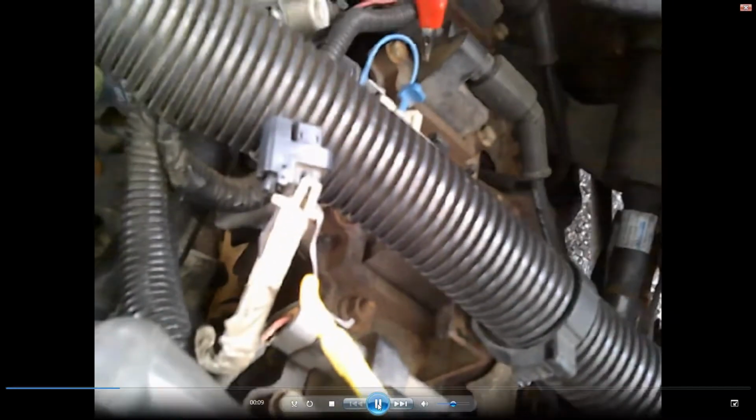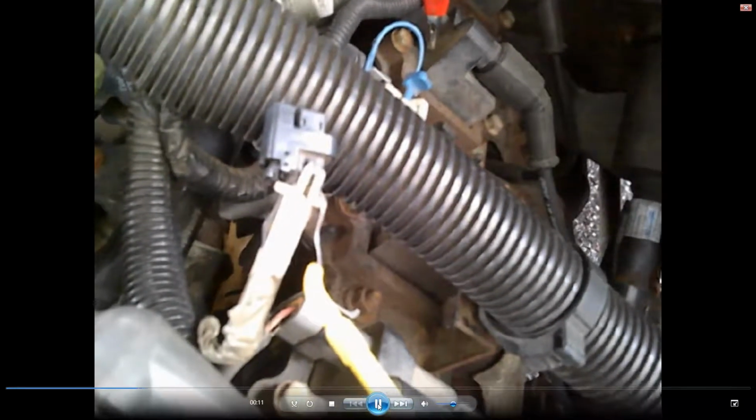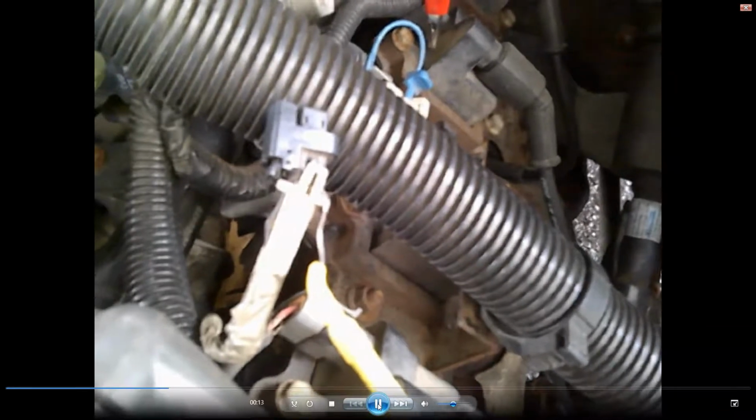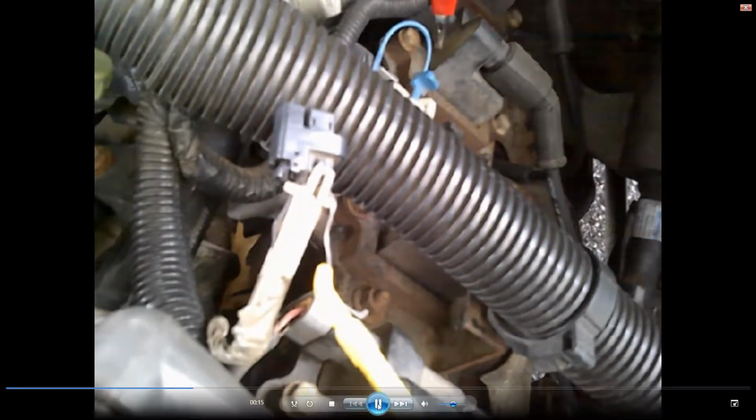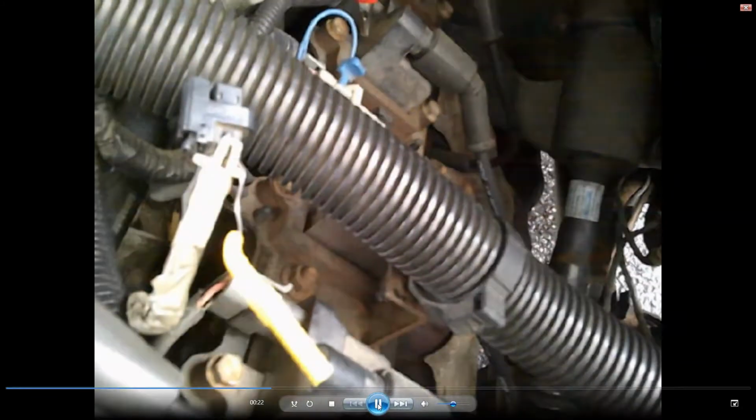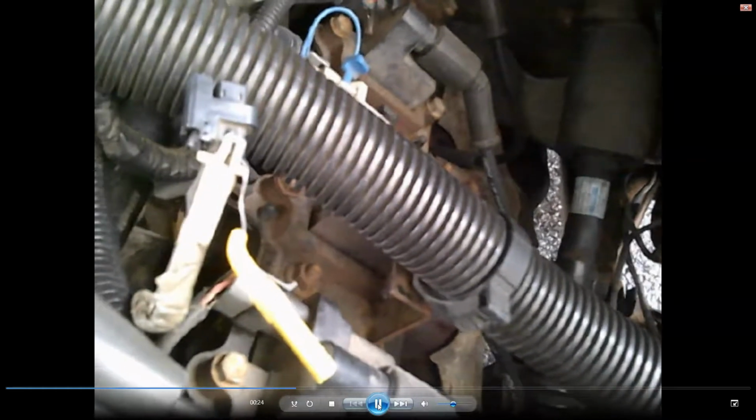Okay, so I've been having a lot of fun here. This is my connector for the fuel injector. If you look at your diagram on the video, you'll see the pink wire is coming from that fuse. I used a back probe to get behind the connector. It only took me 10 minutes to finally get it in there.